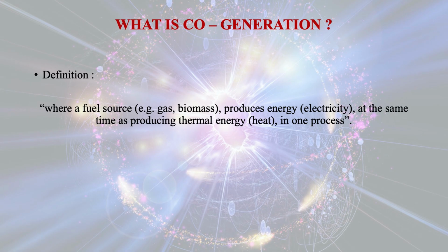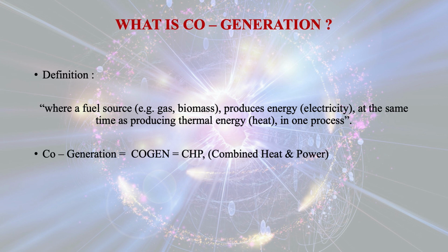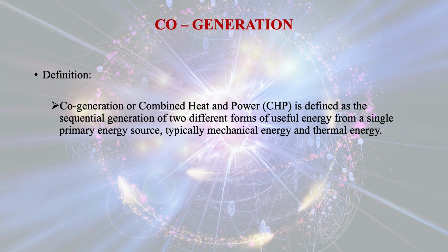Dear learners, let us begin our discussion. The practical ideal regenerative Rankine cycle is achieved by extracting steam from the high pressure turbine at various points, and it is used for heating the feed water. The device where the feed water is heated is known as regenerator. The regenerator also deaerates the feed water, which is necessary to prevent corrosion in the boiler.